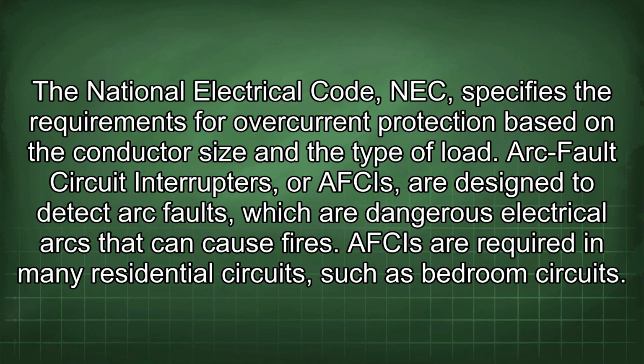The National Electrical Code (NEC) specifies the requirements for overcurrent protection based on the conductor size and the type of load. Arc fault circuit interrupters, or AFCIs, are designed to detect arc faults, which are dangerous electrical arcs that can cause fires. AFCIs are required in many residential circuits, such as bedroom circuits.